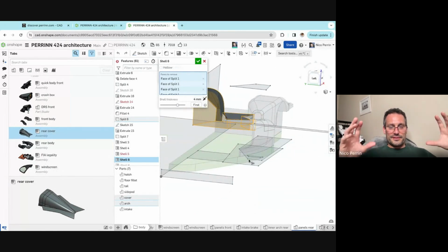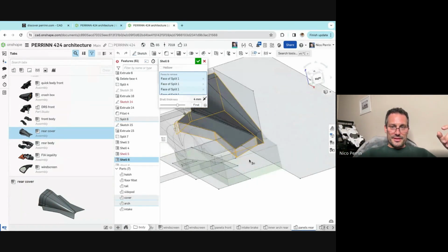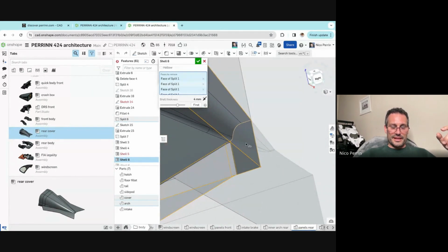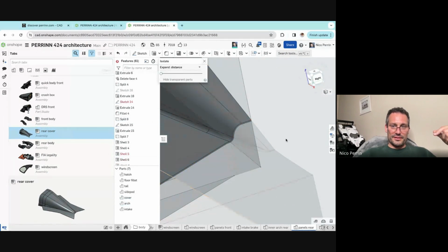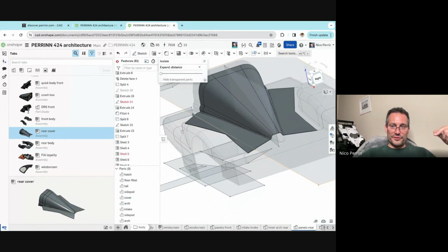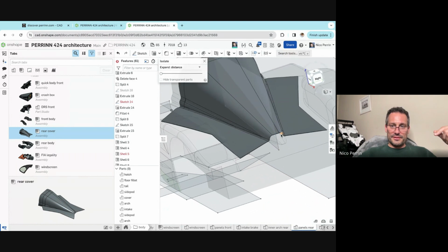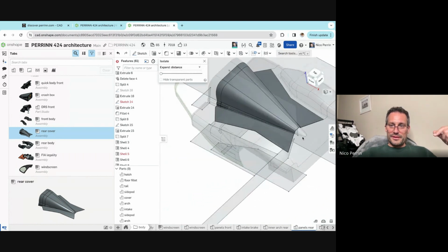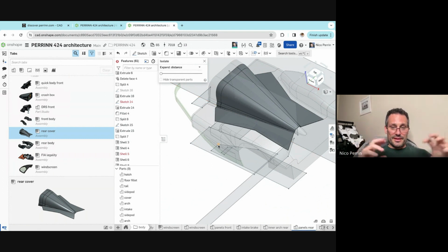What I've done is I started from a master, something that's very heavy and thick, and I clicked on all the faces I wanted to delete. And now you can see that that face hadn't been selected properly, because the new shape for the engine cover has created this new face. Remember before, the top part of the cover was low enough that this face did not exist. So I would come back here, select this face, click OK. And now the engine cover would be finished properly. And it's got the new shape. And the whole document has been updated and everything's translated.